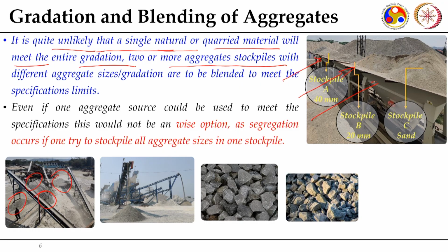They have to be kept in the cold fill bins. This we will discuss when we discuss the construction of these particular mixes. During production and construction, these aggregates of different sizes are stored in these cold fill bins. Now, this is a plant. It can be a wet mix macadam plant or it may be a hot mix plant, where the aggregates which are to be used are stored in these different cold bins. Cold bins because they are at ambient temperature.